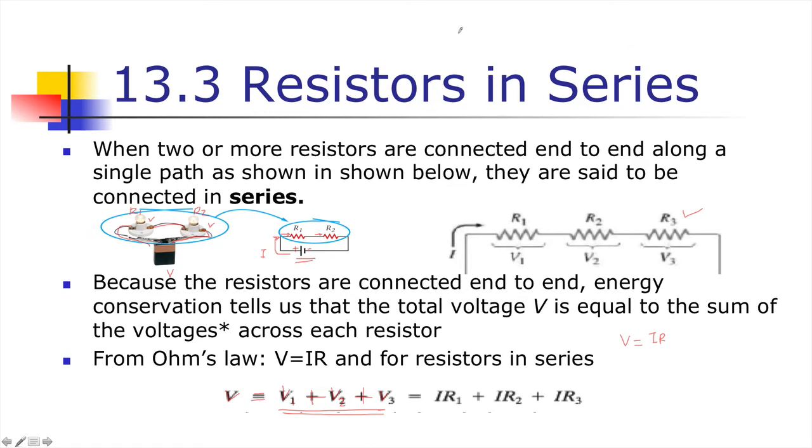Sometimes you might have encountered faulty Christmas lights. If one of the bulbs is dead, several of them are not working. Why do you think that is happening? The reason is, if this bulb is dead, there is no passage of current to the next one, because this portion is connected in a series fashion.